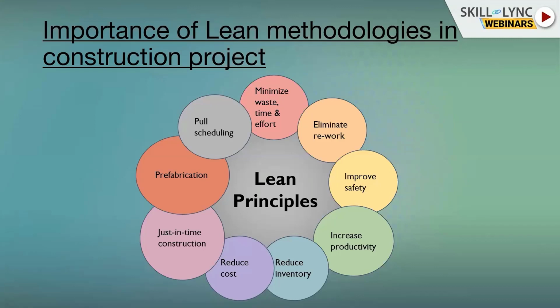In a construction scheduling context, just in time requires alignment and balance between project items that are considered long lead, that is, the materials taking comparatively longer time to be available at site after being ordered, and those that are more readily available. So Lean maintains a balance between these two items. The JIT, that is just-in-time method, also requires that the suppliers and contractors collaborate at a higher level than in regular construction methods. And it requires that all project supplies are up to the standards. This helps to prevent project delays due to unusable materials and helps to ensure that contractors deliver a quality product or service with reduced defects and maintenance needs over the life of the product.